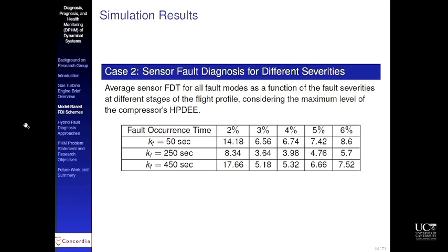Here is another result which shows this: when the severity of the fault increases, and again this is intuitive, the detection time decreases. When the fault is more severe, it's easier to detect. Because the problem in diagnosis is not when you have a significant level of fault. If your motor stops working, anybody who's monitoring it can say, oh, there is a fault. There's no current, there's no torque, there's nothing. It's not rocket science to do that.